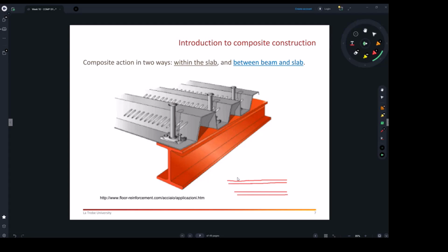And the metal deck is again just placed on top, and that seems to be for me a heavy duty metal deck. And to make sure they are bonded together, they use the shear studs, because they want a composite between the slab and the steel beam. So later on, they're going to come and pour the concrete here.